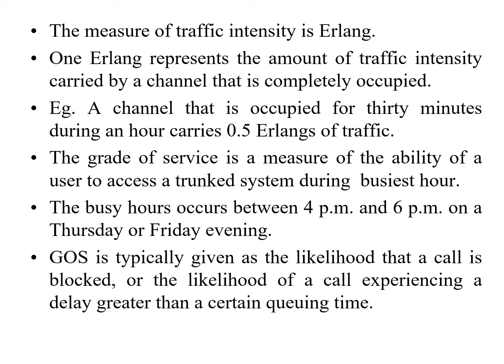The measure of traffic intensity is Erlang. One Erlang represents the amount of traffic intensity carried by a channel that is completely occupied. Example, a channel that is occupied for 30 minutes during an hour carries 0.5 Erlangs of traffic. The grade of service is a measure of the ability of a user to access a trunk system during the busiest hour. The busy hour occurs between 4 p.m. and 6 p.m. on a Thursday or Friday evening. GOS is typically given as the probability that a call is blocked or the likelihood of a call experiencing a delay greater than a certain queuing time.